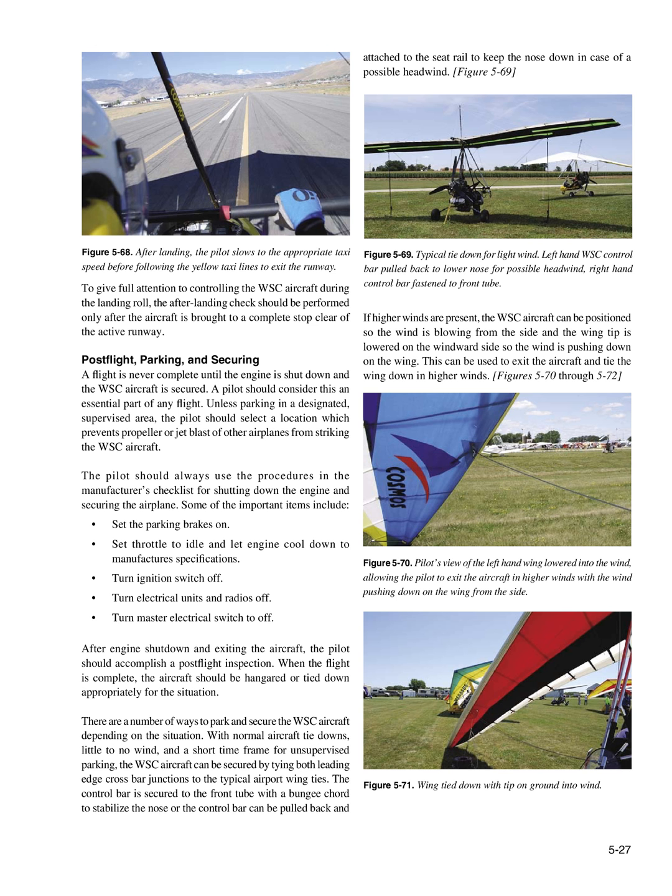Some of the important items include: set the parking brakes on, set throttle to idle and let engine cool down to manufacturer's specifications, turn ignition switch off, turn electrical units and radios off, turn master electrical switch to off. After engine shutdown and exiting the aircraft, the pilot should accomplish a post-flight inspection. When the flight is complete, the aircraft should be hangared or tied down appropriately for the situation.